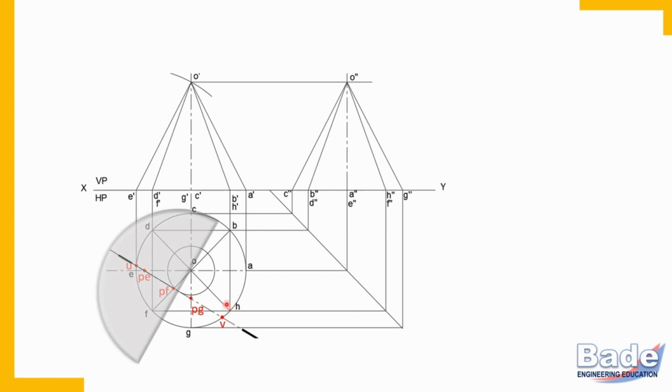Try to understand. Use a protractor. Set the axis of symmetry of the protractor with the cutting plane line, and the straight edge of the protractor set it with point O, and draw a line. This is that extra generator. Now label that point on the base edge as M. So like those 8 earlier generators, OM is also a generator of the cone.